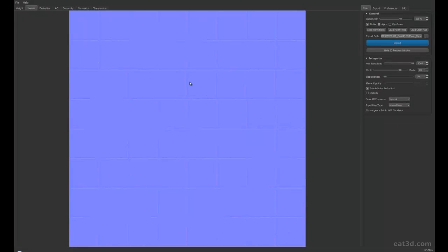So what you can do is you import that, and now there's a maximum iterations button here, and I just pull that slider right to the top, and it'll work out the amount of iterations that it needs to process that normal map, and that works out at 607. It doesn't matter if it says 1000 there, I just make sure it's 607. Okay, so that's a height map. So we've got another height map, which would be good to use as a mask.